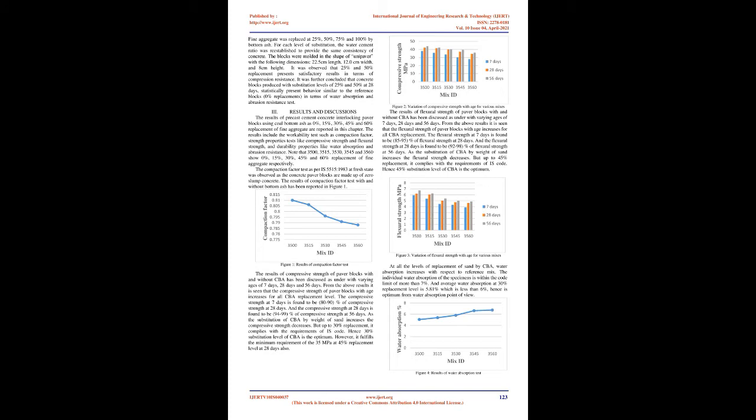Anani et al. studied the use of bottom ash for replacing fine aggregate in concrete paving blocks. In phase I of the study, mixtures of cement and bottom ash passing 2 mm and 5 mm sieves were made with ratios of 1:3, 1:4, and 1:5. Tests were conducted for compressive strength at 7, 14, and 28 days. It was concluded that paving blocks made with bottom ash passing the 5 mm sieve have better compressive strength than those with 2 mm ash, due to less surface area with larger particle size.